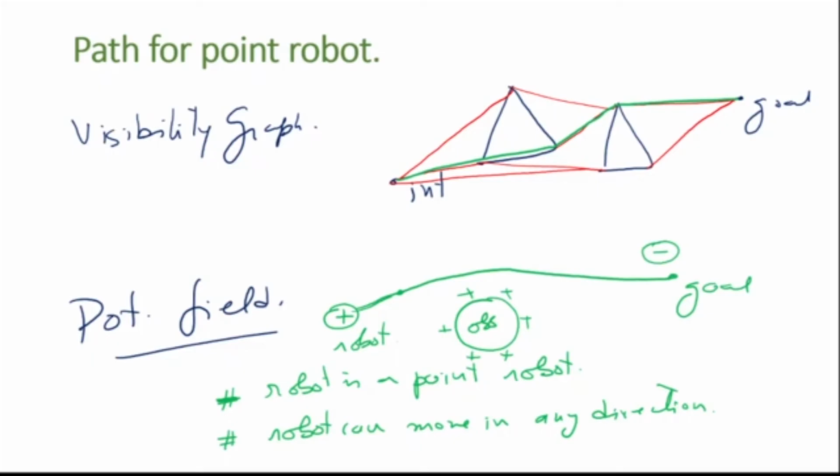Okay. Now, there are robots which can move in any direction, which are holonomic robots. But there are also robots which cannot move in all directions, which are non-holonomic robots. Okay. So, for example, a car can go straight and it can turn, but it cannot go sideways. Okay. So, today we'll be looking at path planning and especially whether it is possible to take this kind of non-holonomic robots and position them wherever you want. And that is what we talk about in terms of controllability.